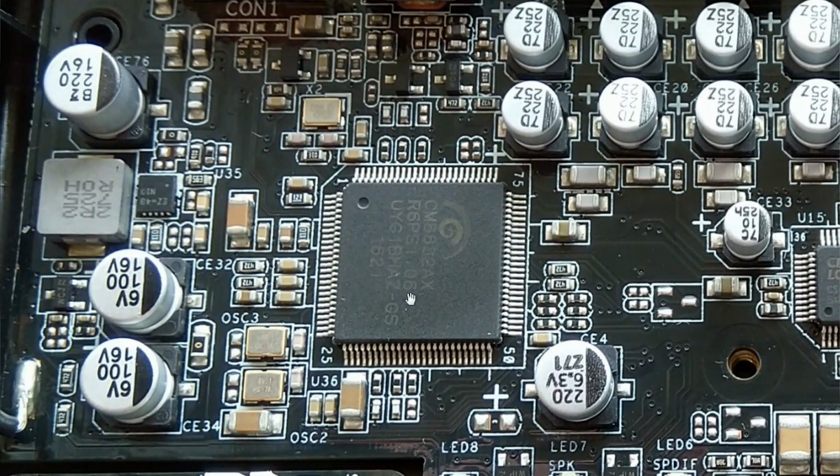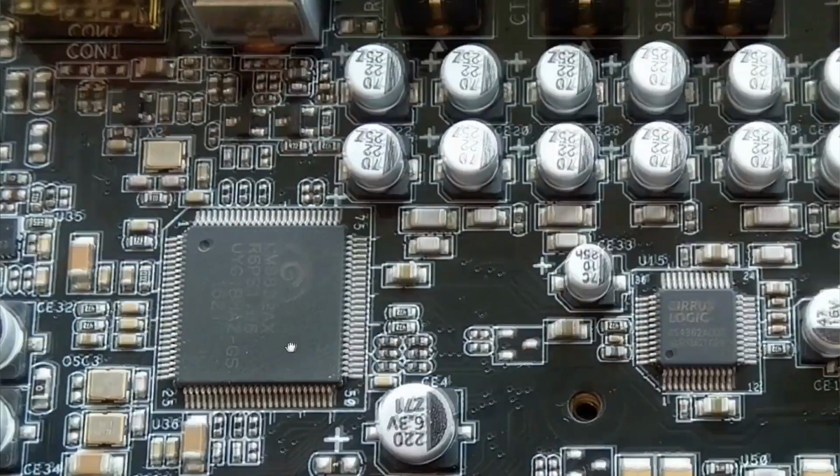And if we go over here, this is the main sound card controller. This chipset basically does everything you need in a sound card, and it's a CM6632. It even comes with a built-in microcontroller. It's got I/O ports, and you can program it and all sorts of things. It basically does everything digital. It does the USB, and it generates all the clocks for the DA and AD converters. You can see we've got a number of crystals over here.